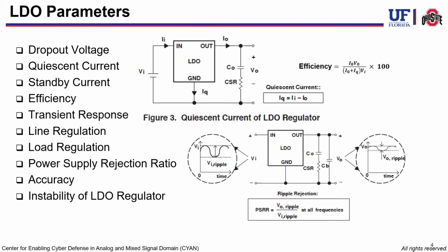These are some of the most important LDO parameters that can be used to compare aging effects between a new AMS chip versus a counterfeit or aged AMS chip. In previous works, the power supply rejection ratio proved to be effective to detect counterfeit chips, but it also proved to be impractical as it required extensive data measurement over different frequency ranges using very ineffective external measurement mechanisms.